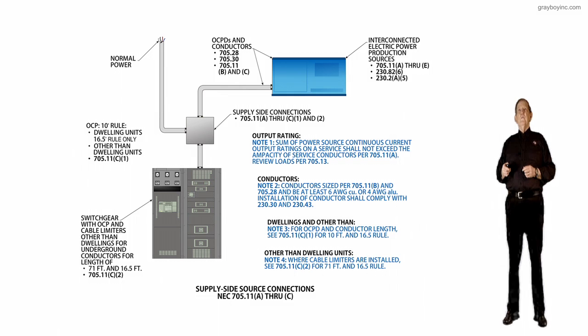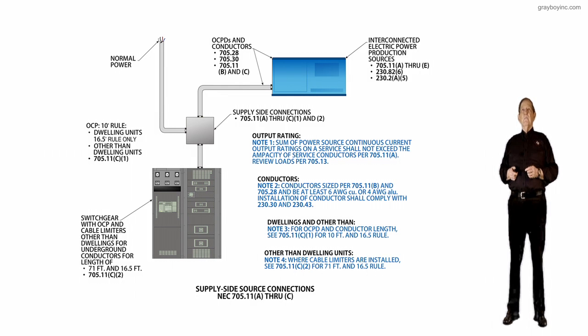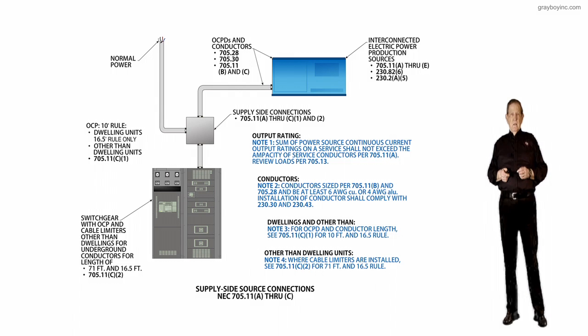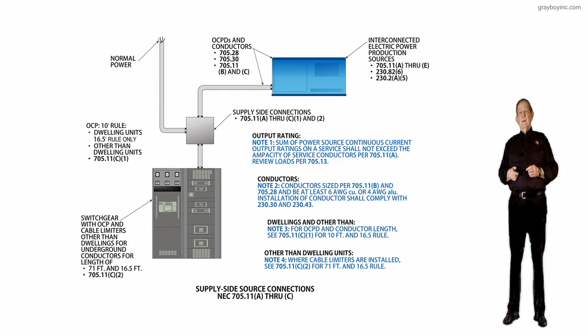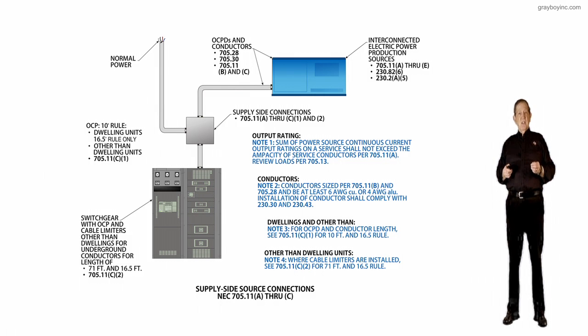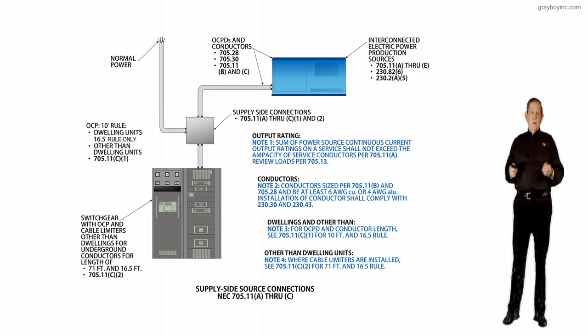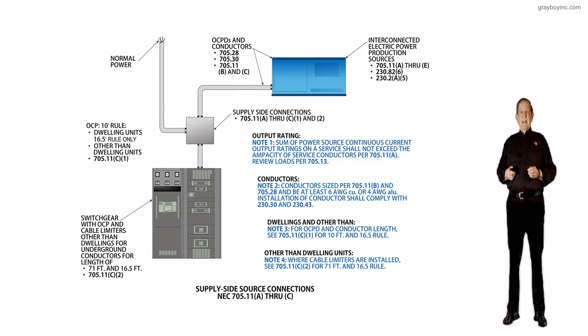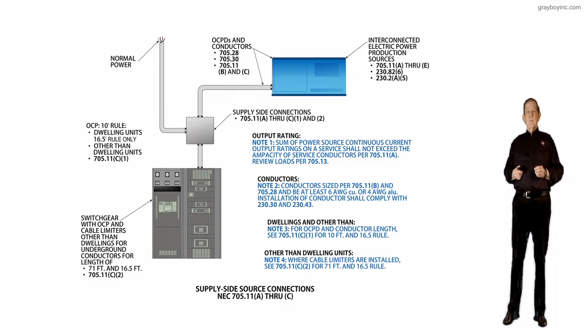Notice 705.28, 705.30, 705.11(B) and (C) contain the requirements so that we do not make a mistake in sizing these conductors, sizing the overcurrent device ahead of the conductors, and sizing the raceway system that encloses these conductors from the generator to the interactive inverter. And again, remember, the inverter might be 3-pole or 4-pole as defined and outlined in 250.30 informational notes 1 and 2.